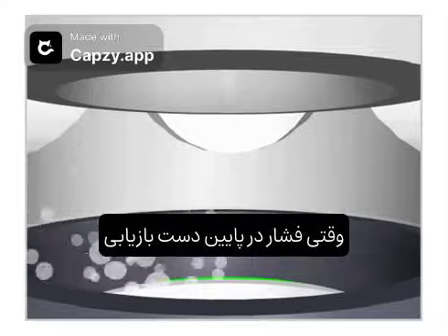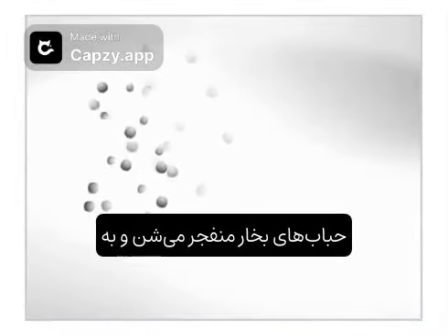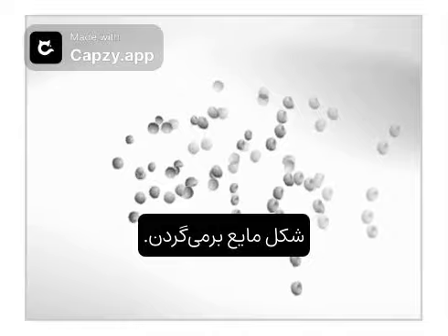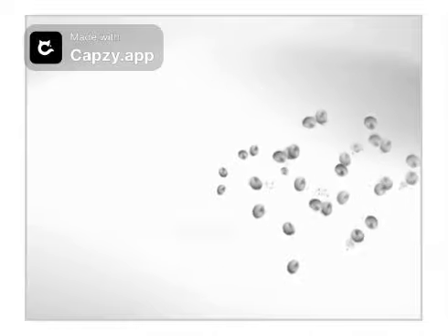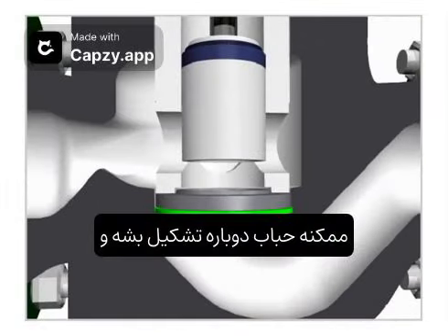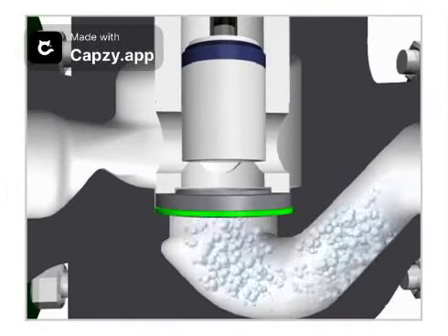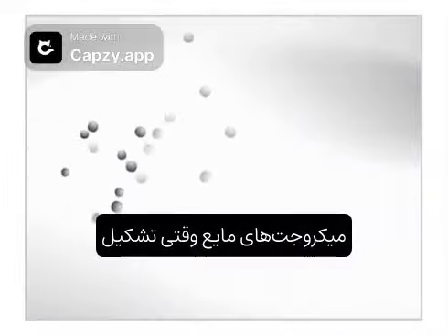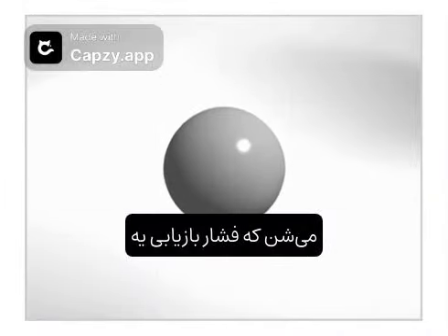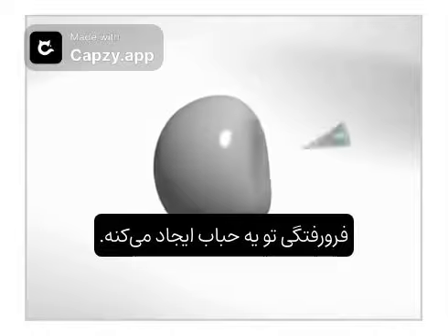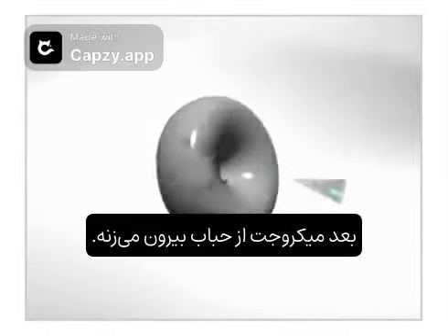When the pressure recovers downstream, the vapor bubbles implode and return to liquid form. After the initial bubble formation and collapse, the bubble may reform and collapse a second time. Liquid microjets form when the recovering pressure makes an indentation in a bubble. Then the microjet bursts through the bubble.